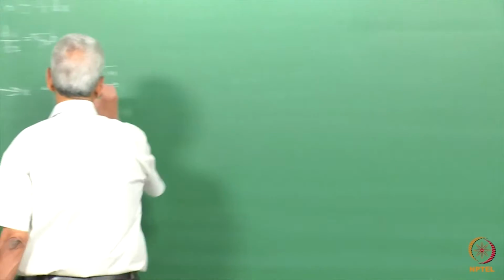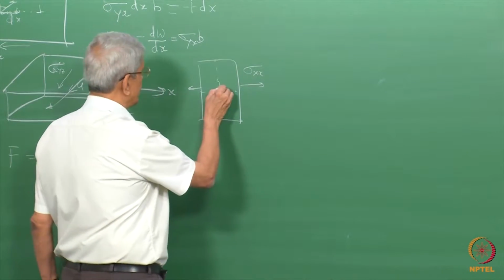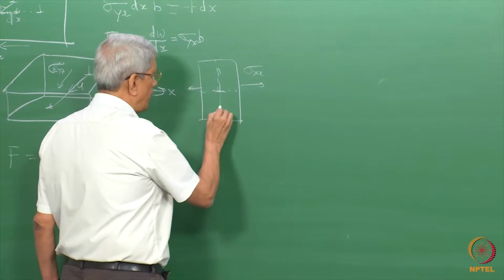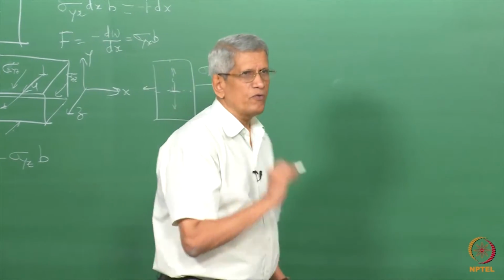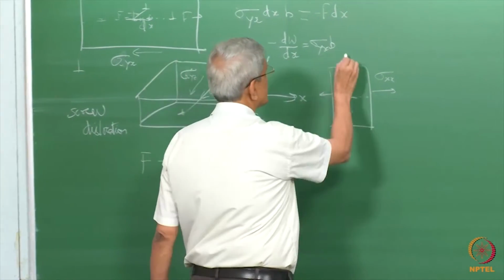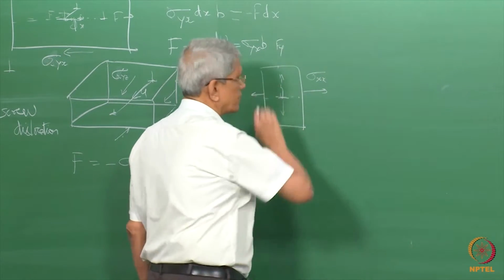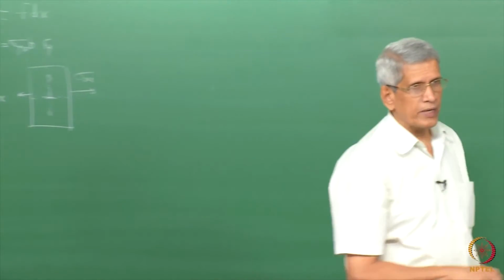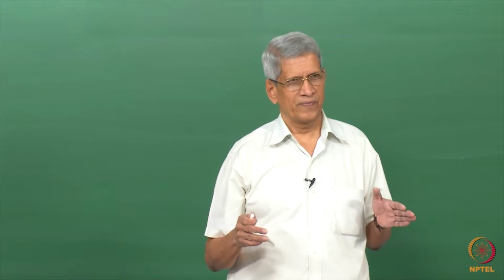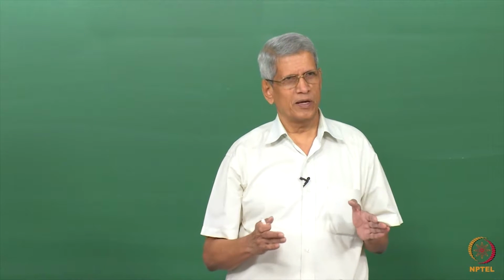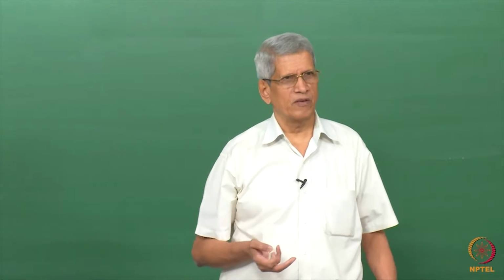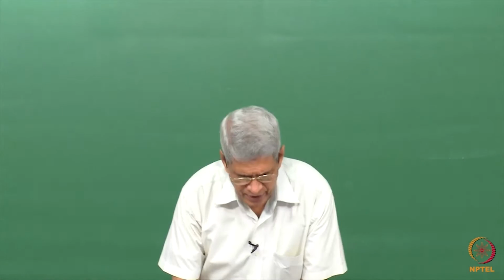That means that on the dislocation line, a force is acting which makes it move up or down. So here the force is acting in the x direction, and here the force is acting in the y direction. We will call it Fy as the component. The application of a tensile or compressive stress on the sample essentially makes the dislocation move up or down. This is what we call a non-conservative motion, or a climb process of a dislocation.